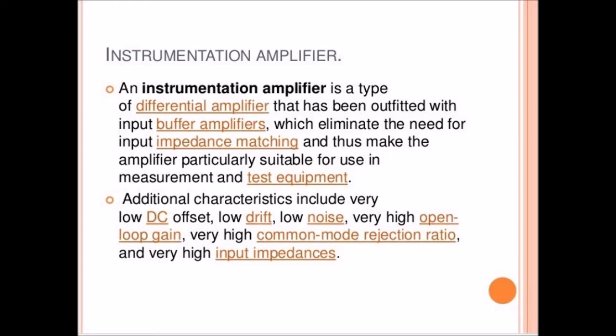From this point of view, we need to provide an impedance matching and buffer circuit. The differential amplifier circuit with a buffer circuit is called an instrumentation amplifier.